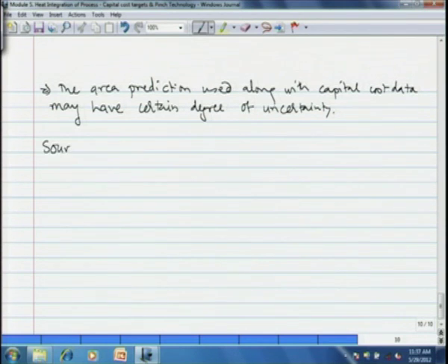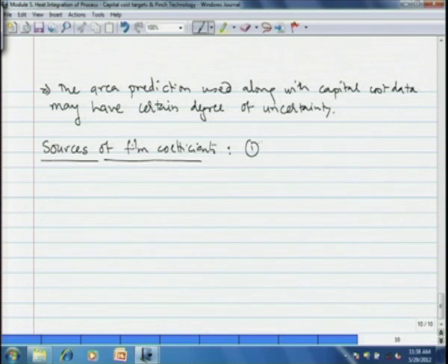Now, the only issue that we are left with are the sources of film coefficients hi and hj. Now, there are many sources here. One can use the tabulated experience values, order of magnitude coefficients, which are listed in standard books such as Perry's Chemical Engineering Handbook, tabulated values which are maybe of order of magnitude accuracy.